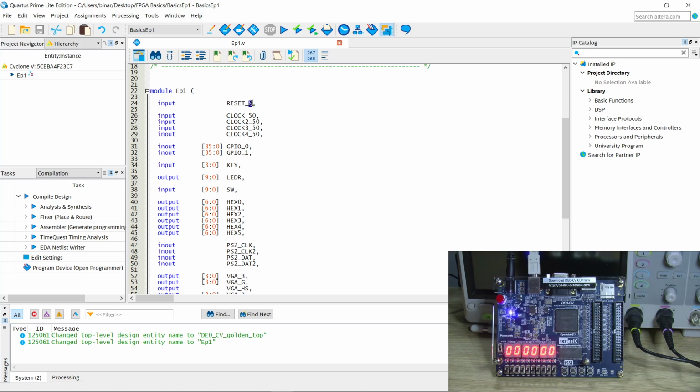And the fact that it's got an N after it, _N, is basically indicative of the fact that it's a low active signal. So a binary 0 or a low signal will actually trigger the reset, whereas it's normally going to be high when we're not resetting. That will make a little bit more sense when we go through and start using it if it's not already.